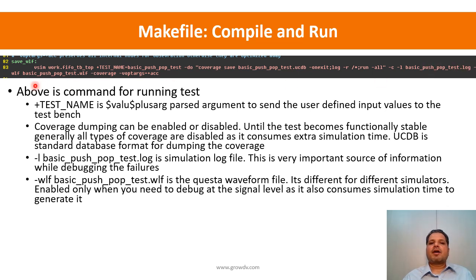And then we are specifying -WLF. -WLF is the waveform format for the Questa simulator, and we are specifying the test name.wlf. WLF is an extension used for waveform files in Questa.